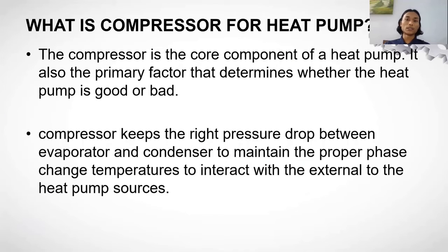So what is a compressor for a heat pump? The compressor is the core component of a heat pump. It is also the primary factor that determines whether the heat pump is good or bad. Why do I say the compressor is a core component? It is because the compressor keeps the right pressure drop between the evaporator and condenser to maintain the proper phase change temperature to interact with the external heat pump source.